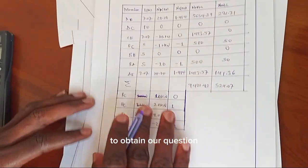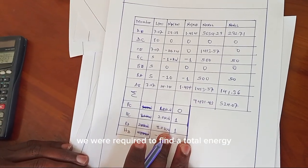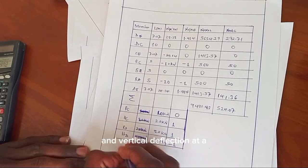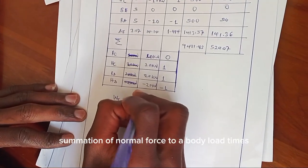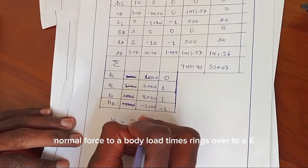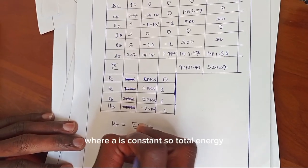Now to answer our question, we were required to find the total energy and the vertical deflection at A. Total energy is obtained by taking the summation of normal force due to applied load times normal force due to applied load times length over 2AE, where AE is constant.